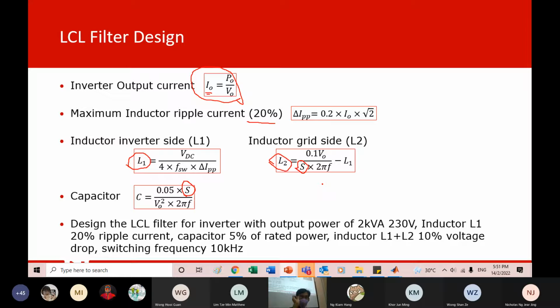You will notice that for grid-connected inverters, they no longer use kilowatts. They don't use real power. They use apparent power, kVA, because it consists of active and reactive components. So don't be surprised when you go and buy a grid-connected inverter: it's 2K, you know how many? 5 kVA. But when you buy off-grid ones, they will tell you how many watts, real power. So that is the main difference between grid-connected and off-grid standalone inverters.